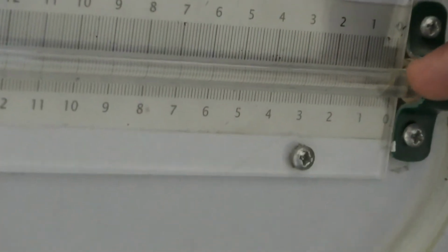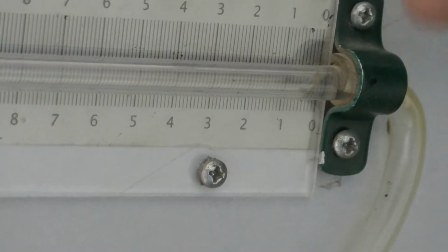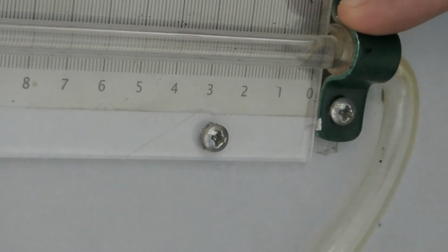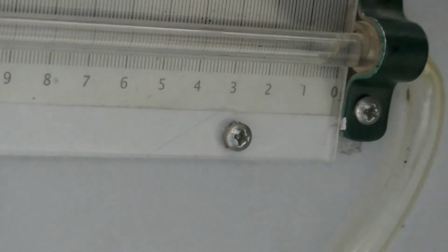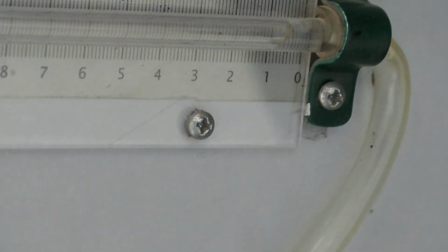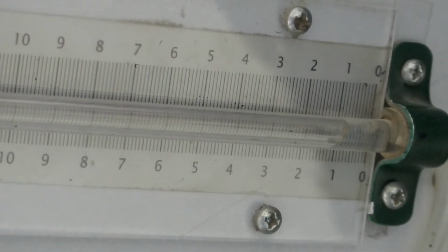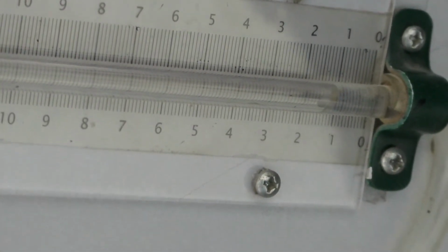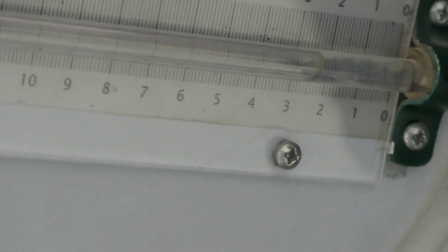As the speed of the motor is increased, the level is increasing. It is now 200 RPM, and now he is increasing to 400, and you can see how much it is increasing at 400 RPM. So like this we have to do from 100, 200, 300 up to 1450 RPM. 1450 is the maximum RPM. At that RPM, it is supposed to be 50 meters per second. The velocity of the wind should be there.